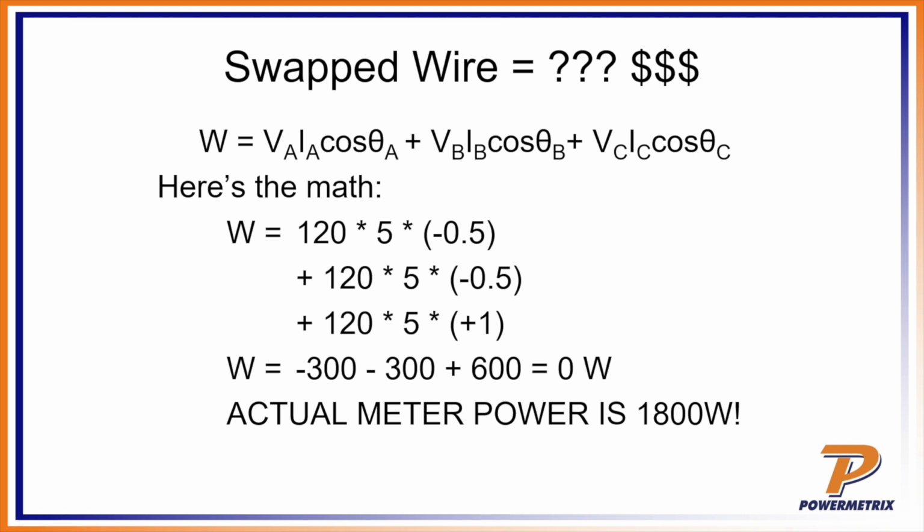So why do we do the site testing, the installation testing, not just the meter? It's because even though the meter is working properly, I'm billing 0 watts, even though 1,800 watts are passing through that meter. Why is it? It's because of that phase angle.